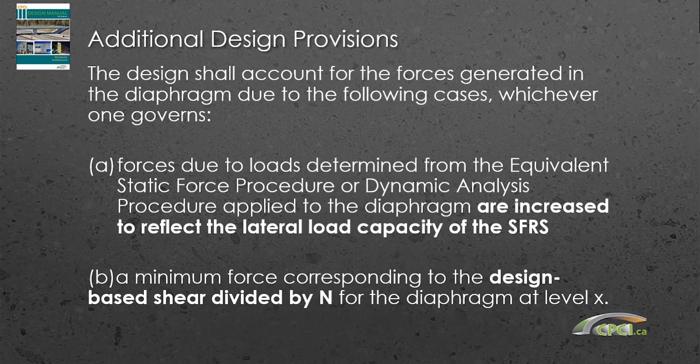And, as far as the load going to the floors, your minimum is your shear divided by N, the number of floors at each level. So I guess it's basically looking at the forces in your diaphragm and either magnifying them based on the capacity of your lateral load resisting system up to the limit of your shear divided by the number of stories.